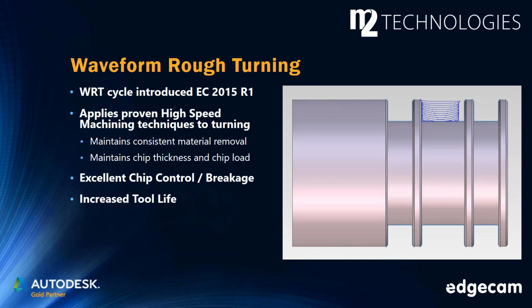Now in milling, we often cite the benefits and they allow us to achieve super high feeds and speeds compared to what we were doing before, and things work great. In turning, the benefit isn't always in higher feeds and speeds because we may be in a situation where we can't really rotate the part in the chuck much faster than it was before. But there are still excellent benefits to that. One of them is that you have really good chip control, really good chip breakage.